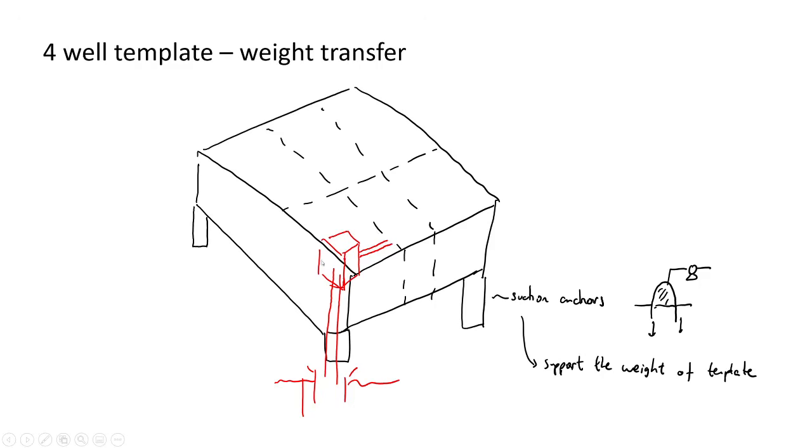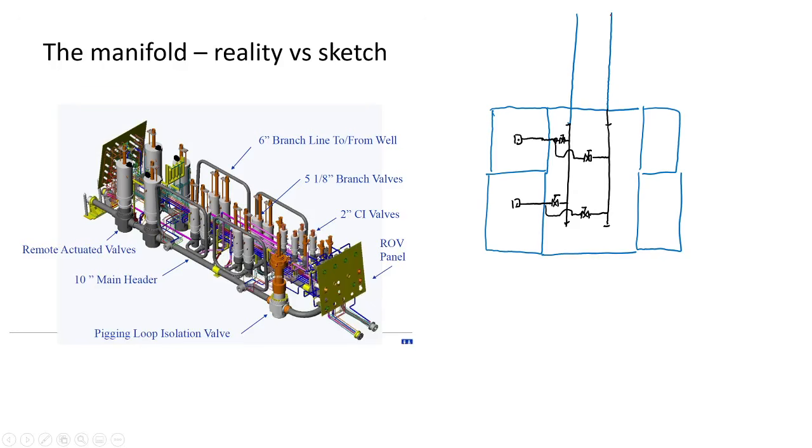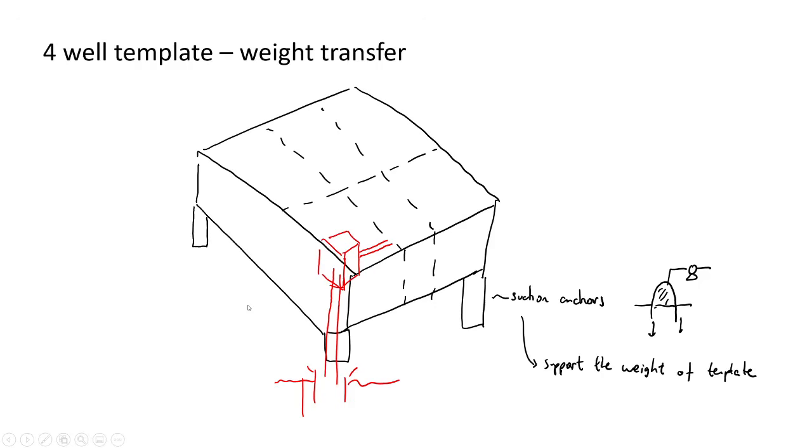The same thing happens if you stop producing: the well cools and is going to shrink, and again this piece is going to deform. So this arrangement is simply to create some flexibility in this line, such that it allows it to go up and down due to the thermal expansion of the wellbore and not break. It gives flexibility to the system to avoid breaking. That's it.